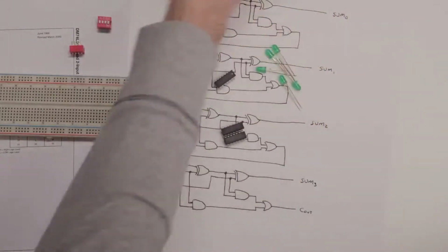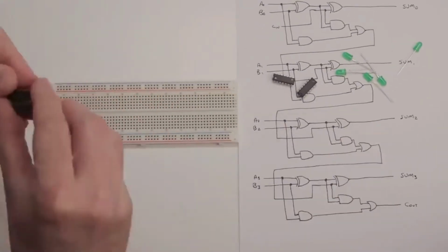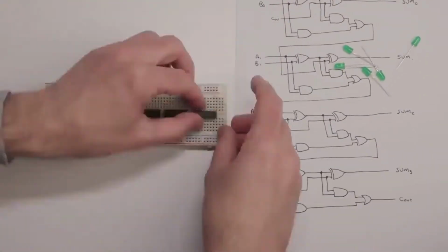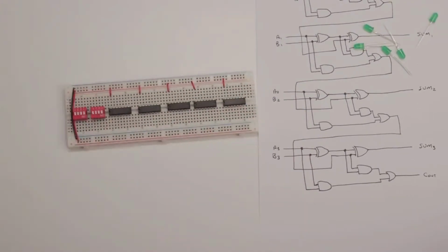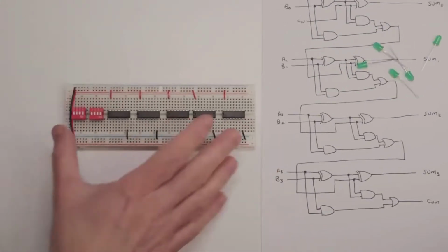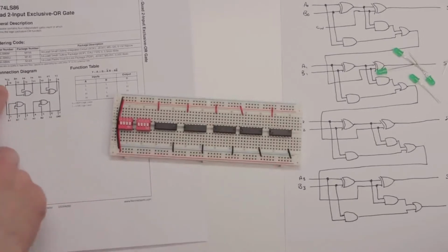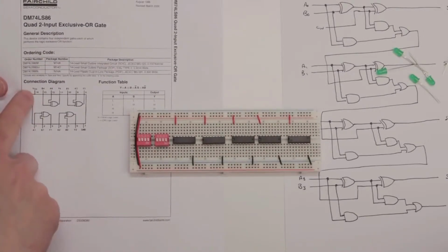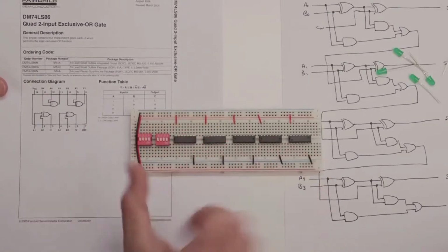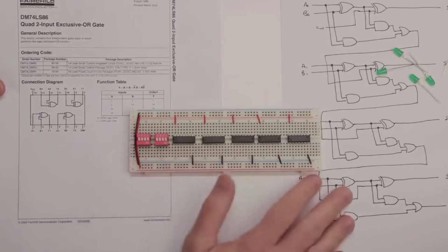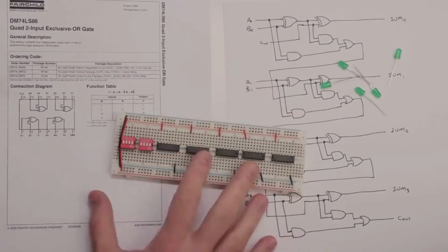So I'm going to go ahead and start getting this thing built on this little breadboard here. I'll just start by sticking this stuff onto the breadboard. Okay, at this point I've got everything on the board and all the chips are powered. Each of these chips has a VCC, which is the positive voltage, and then the ground. Each of those is connected for each of these chips. Everything's on the board. So I'll go ahead and wire up the first of the adders, and we can play with that one first, and then we'll do the rest.